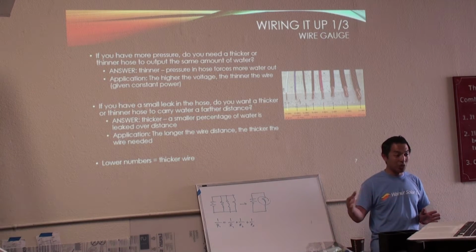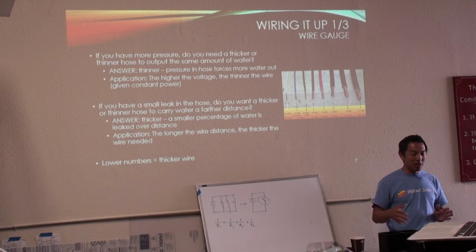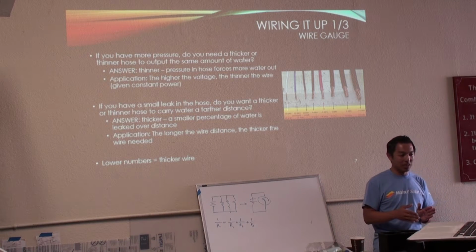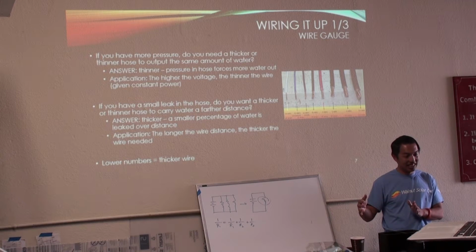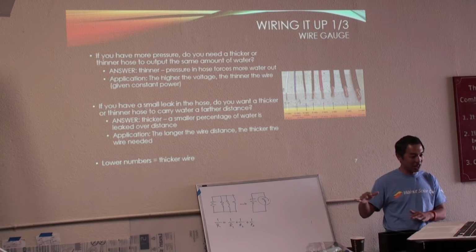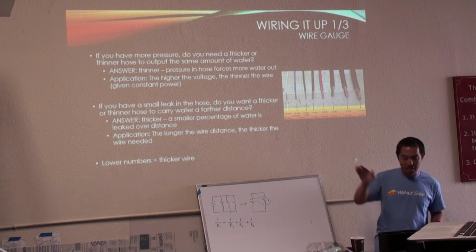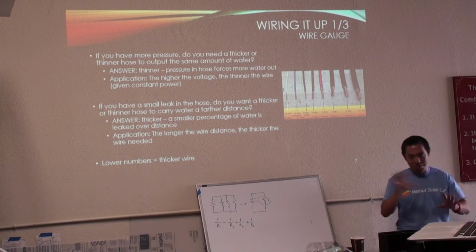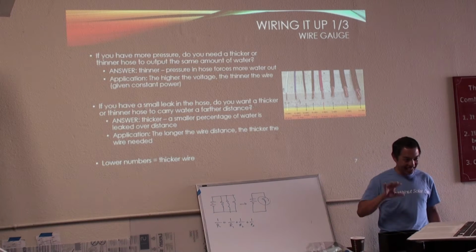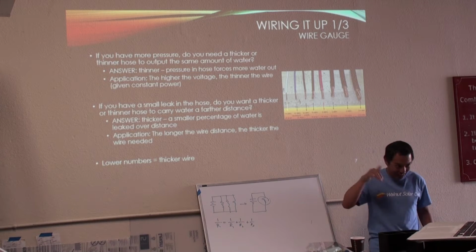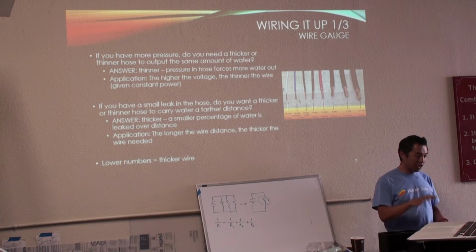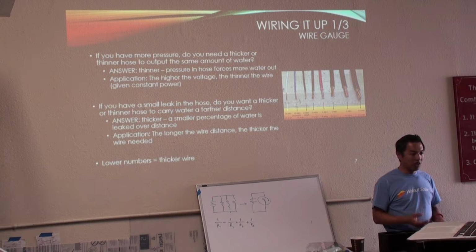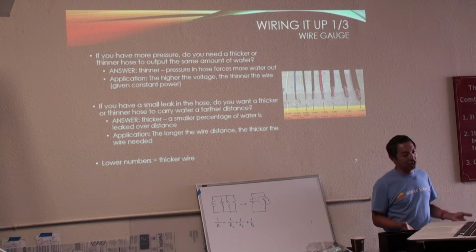If you charge at 20 amps, it will probably take a little less time to get fully charged, up to the peak. At the very top, I can't force the rest of it in, so you have to adjust for that.